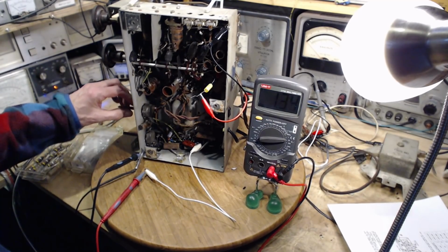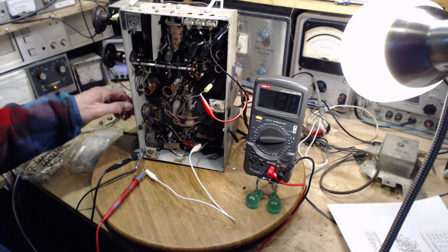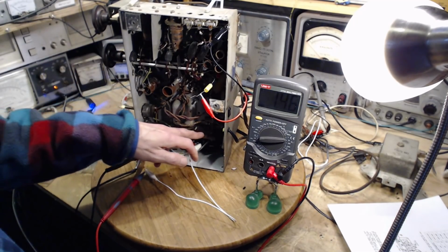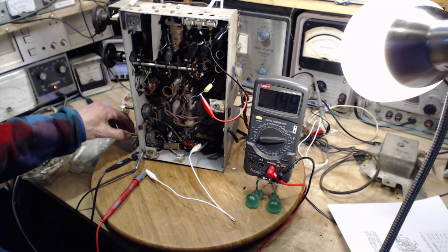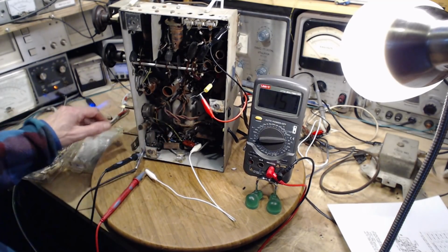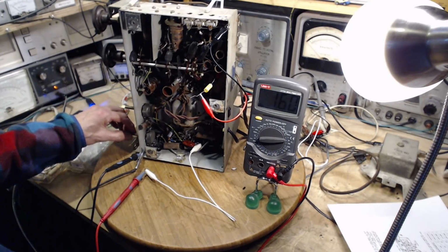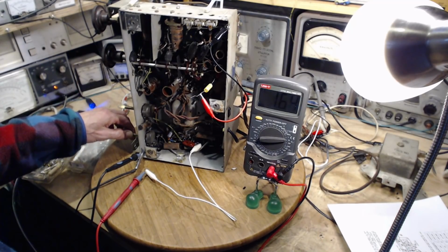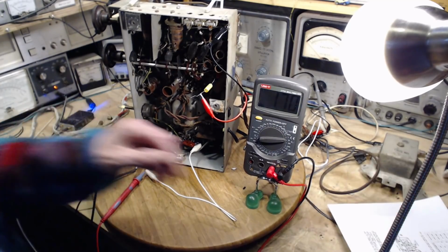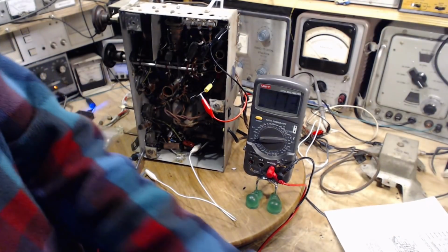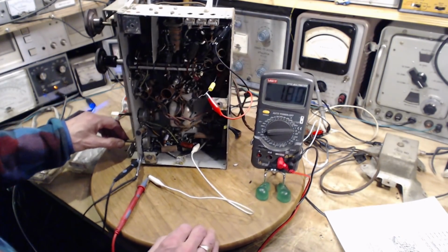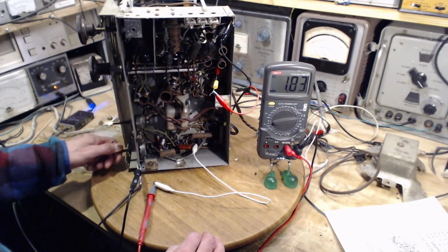So where's a 3? Where's that voltage coming from? It could be coming right from these capacitors. That's awfully high though. These capacitors get moisture in them, they can turn into little batteries. They're crappy batteries, but some of them are in high impedance circuits, and it doesn't take much charge to throw things off. So a crappy battery that can deliver a tiny charge maybe is enough.